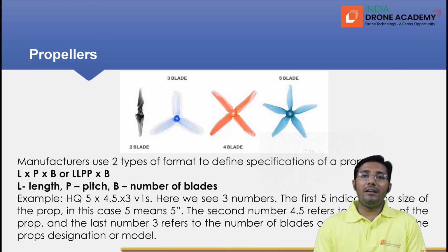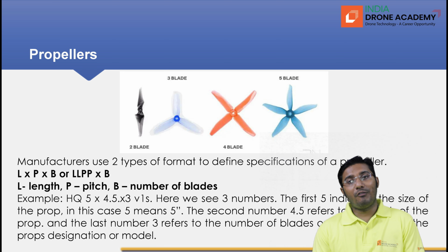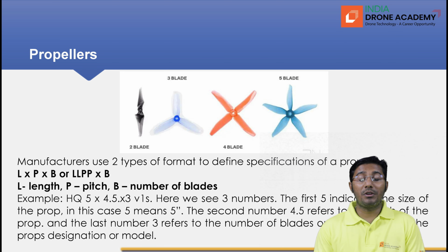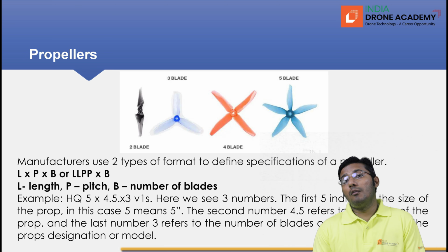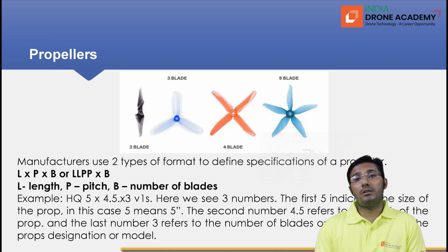Propellers can be 2-bladed, 3-bladed, 4-bladed, 5-bladed. It depends upon the type of operation for which the drone is being used. Racer drones have different types of propellers and different designs. However, drones which are used for aerial cinematography or videography purposes need to be very stable and do not go for very high maneuvers. So there, the selection of propellers is entirely based on different factors.